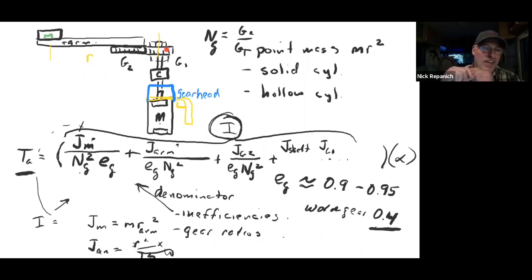We buy gear heads. We pay the money, buy the gear head, and then we get little gears, and this gear head then adds almost zero inertia to the system because the first pass that's directly connected on the motor is a tiny little gear that doesn't have to transmit much torque. And everything after that is reflected through the gear ratio. So, okay, let's stop there.